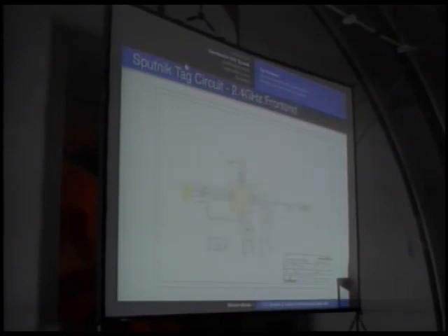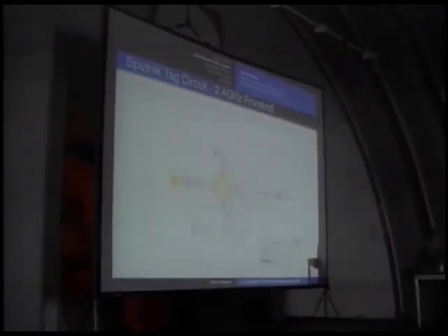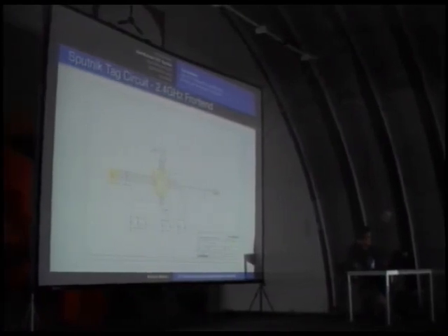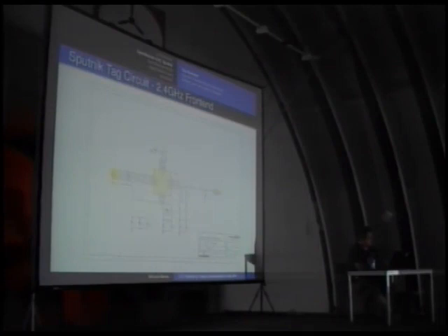And this is the RF front end. So if you do your own schematics, you just have to add this part and connect these I/O lines to your free I/O pins. So that's basically all. You just take the same values and have a look at our layout. And if you want, you can send us your layout and we will have a look at it, whether it's done in a proper way or if you have mistakes, so you don't waste money on PCBs. So if you're interested, just send us your layout and we can check it.